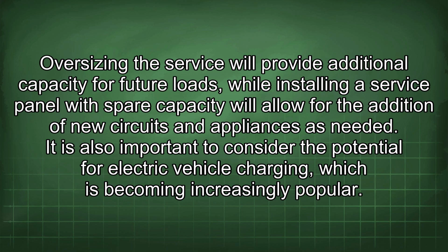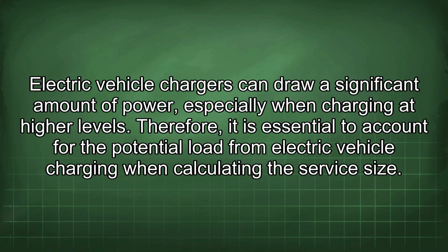It is also important to consider the potential for electric vehicle charging, which is becoming increasingly popular. Electric vehicle chargers can draw a significant amount of power, especially when charging at higher levels. Therefore, it is essential to account for the potential load from electric vehicle charging when calculating the service size.